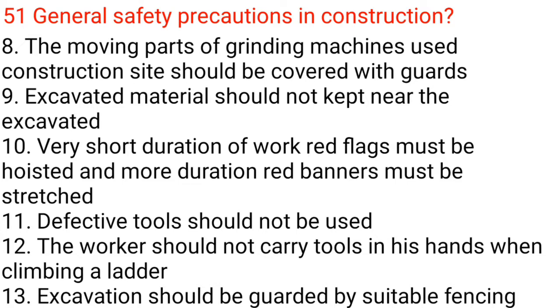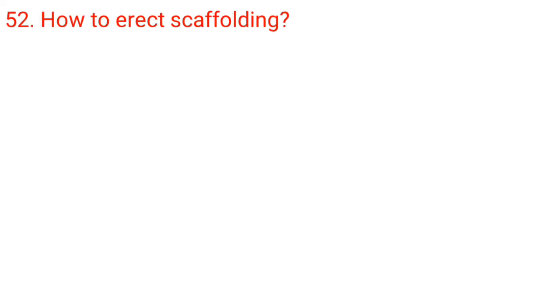9. Excavated material should not be kept near the excavation. 10. For very short duration work, red flags must be hoisted, and for longer duration, red banners must be stretched. 11. Defective tools should not be used. 12. The worker should not carry tools in his hands when climbing a ladder. 13. Excavation should be guarded by suitable fencing.